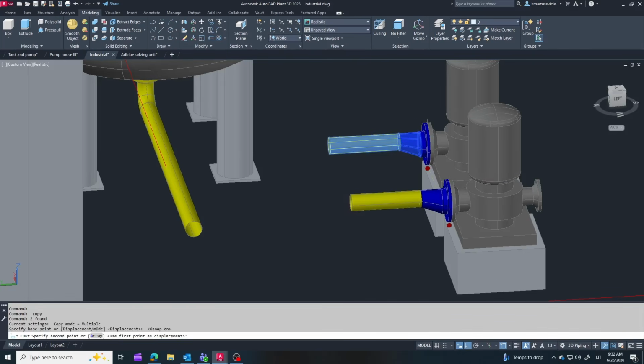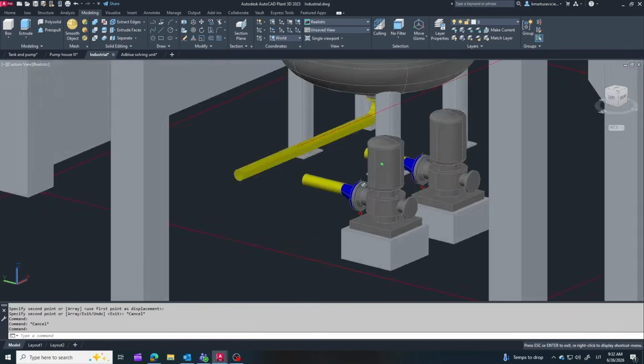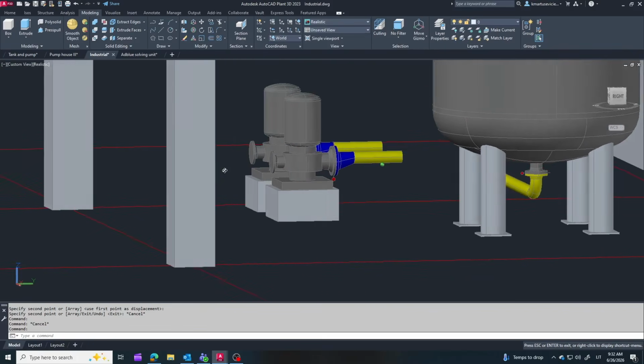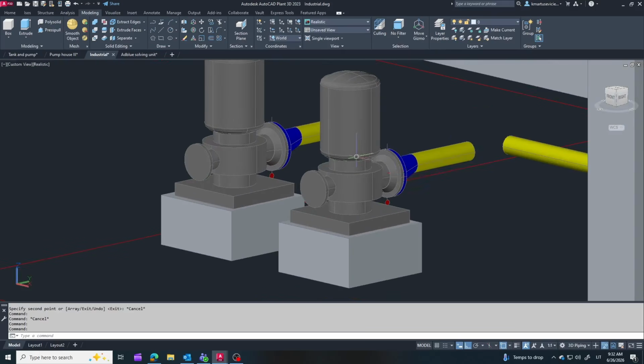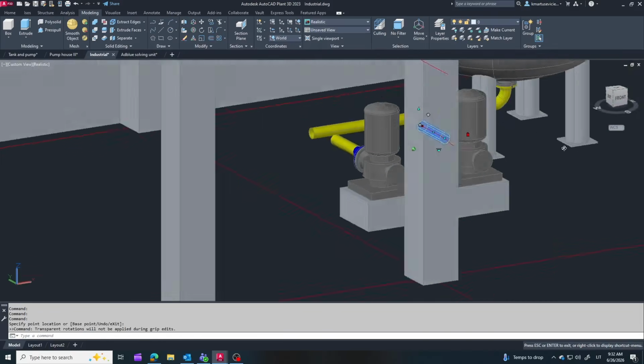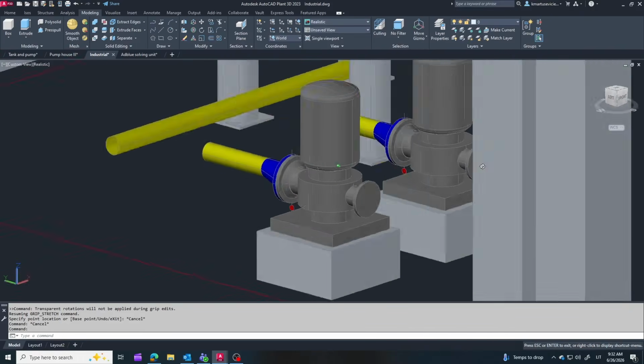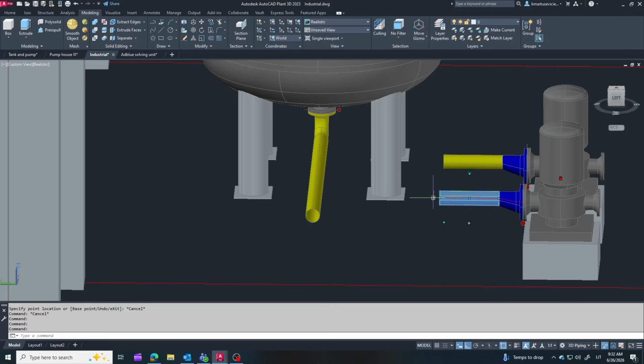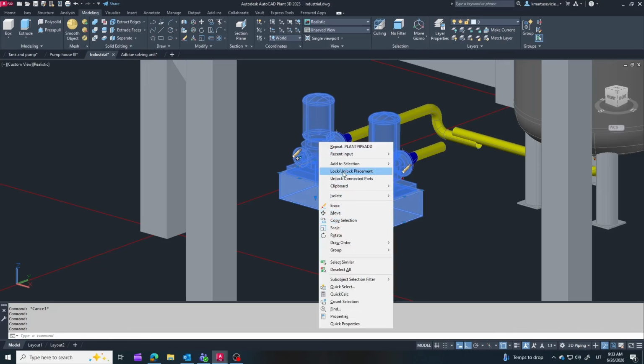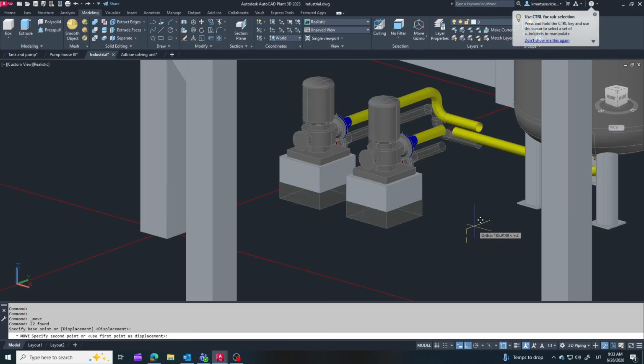Sometimes I measure the distances and route the pipes manually. It gives me full control over the layout, especially in tighter areas. When connecting two open pipes, I use the auto pipe feature. Sometimes it doesn't create the exact routing I want, but that's perfectly fine. I simply let it generate the connection first, and then adjust it afterward.